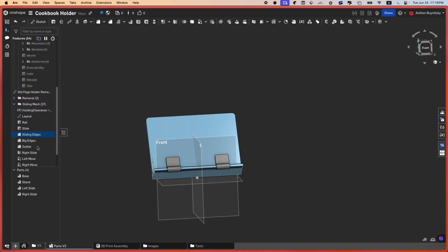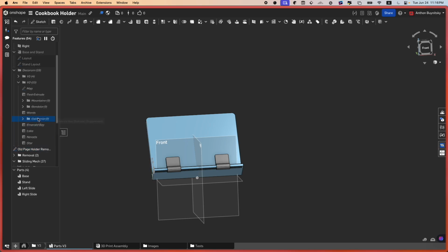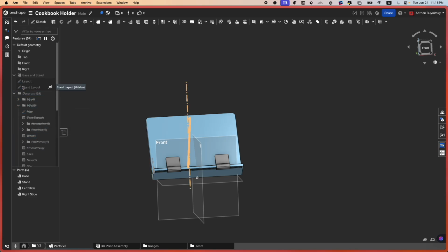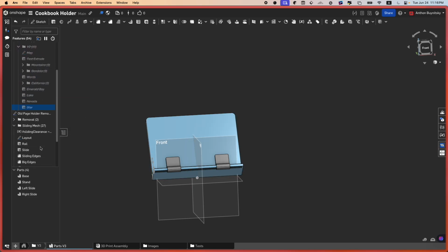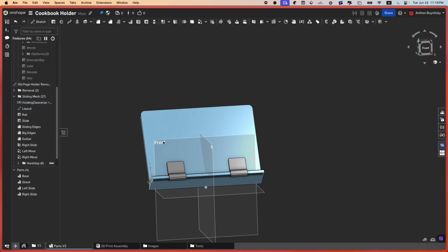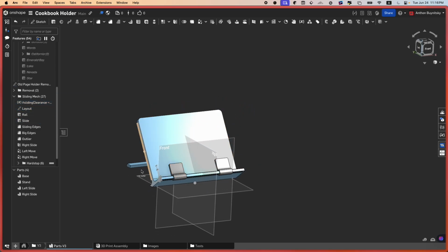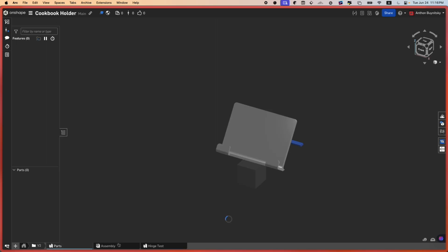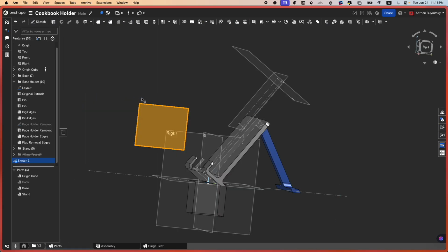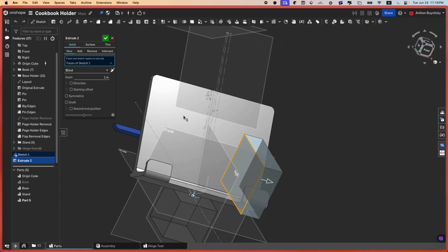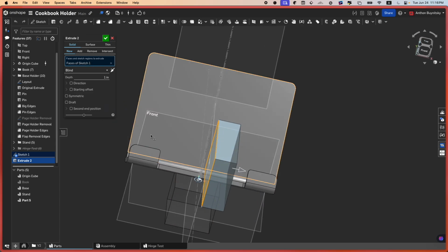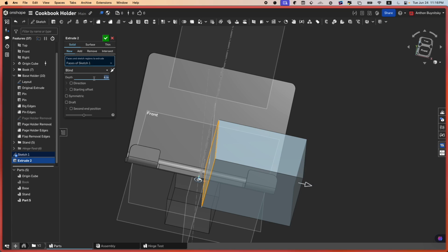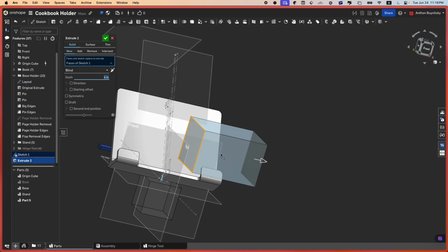And this is really, really important, again, as I said, especially for layout sketching, as we'll get to later. The very first step that you want to do to make your parts symmetric is actually via the extrude function. So let's say I want to make this square symmetric over this right plane, right? And it's 4 inches long. Right now, it is definitely not symmetric, right?